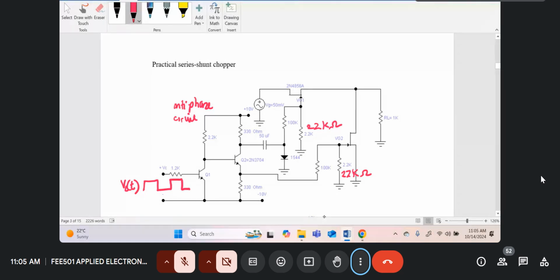IC of Q1 max will just be equal to 20 volts divided by 2.2K, which is approximately 10 milliamps, so slightly less than 10 milliamps.